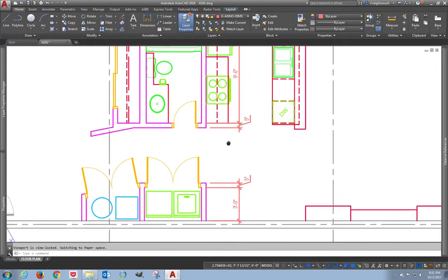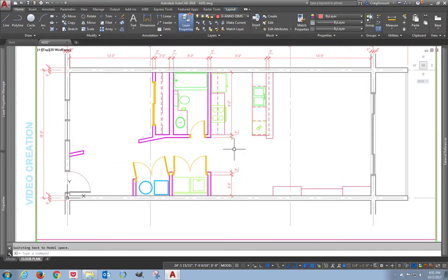because there's two different rules of thought here. One is, because I know this 18'6" dimension is existing, and I know I've got a 4-inch dimension and a 4-inch dimension, that between these 3 dimensions for the existing conditions, I no longer need this hallway to be dimensioned, because the math will just work itself out.